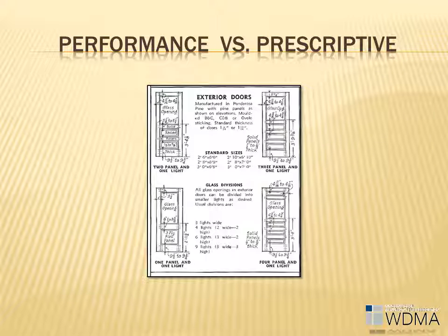The significance to the specifier has to do with the performance emphasis rather than reliance on prescriptive design specifications. Older standards told manufacturers what materials to use and what dimensions each component needed to be. The result was a functional door, but also a product that could not take advantage of innovative assembly or materials. The result also meant that some doors were required to overutilize scarce or dwindling sustainable materials, such as certified wood, hiding most of the volume of these resources inside the door assembly.